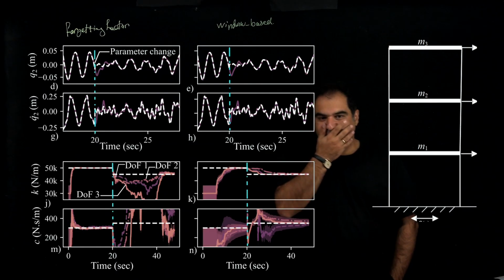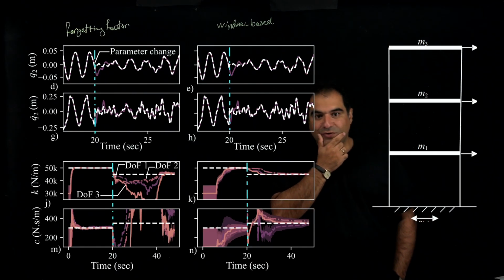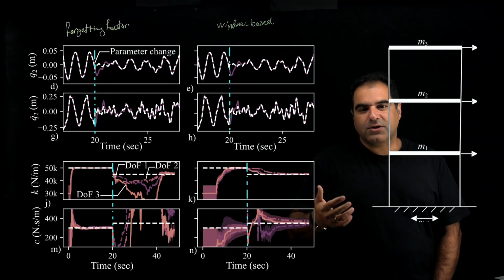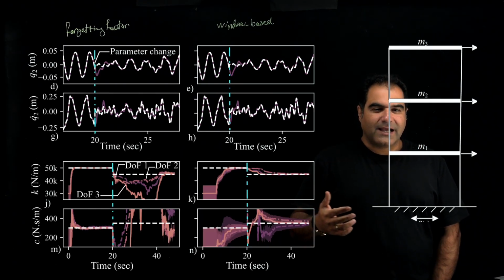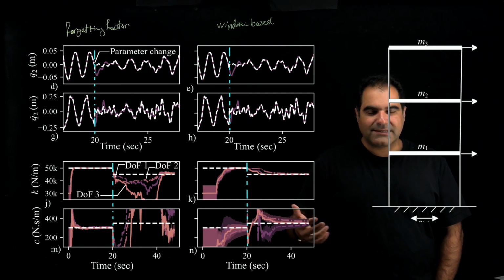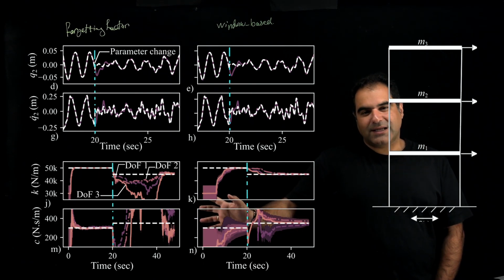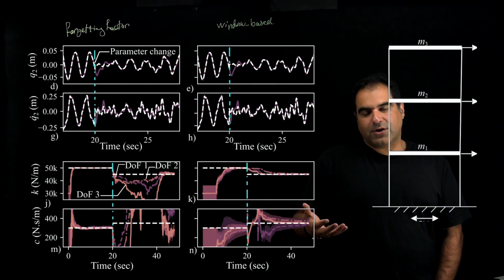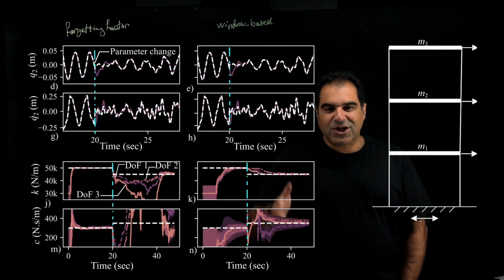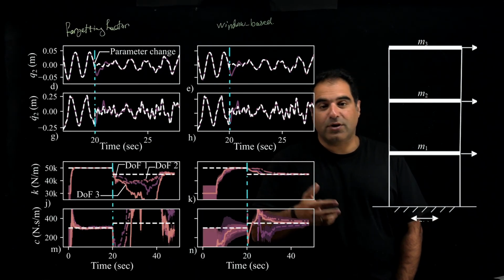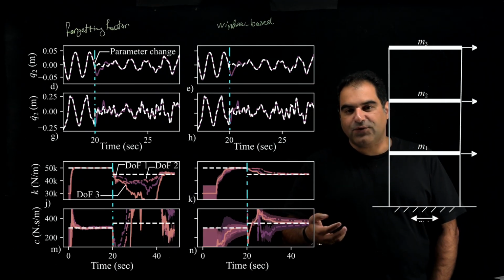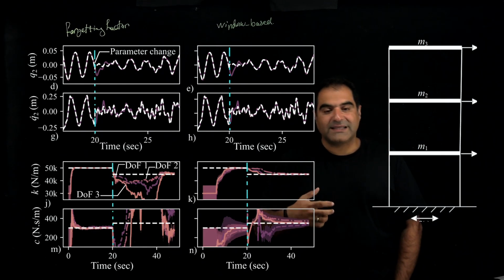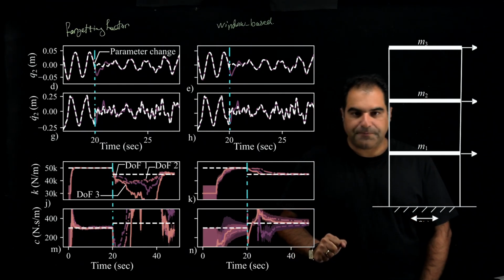Then what we conclude here is that if you have a system where you just want to do a real-time system identification problem, and there is not that much change happening in the system, the forgetting factor technique is the right choice for you, if you have a gradual change or the parameters are not changing over time. But if you have a quick change or damage happening in the system and you are aware that such a thing might happen, the window-based technique is a better choice to go forward with and quantify the level of the damage.